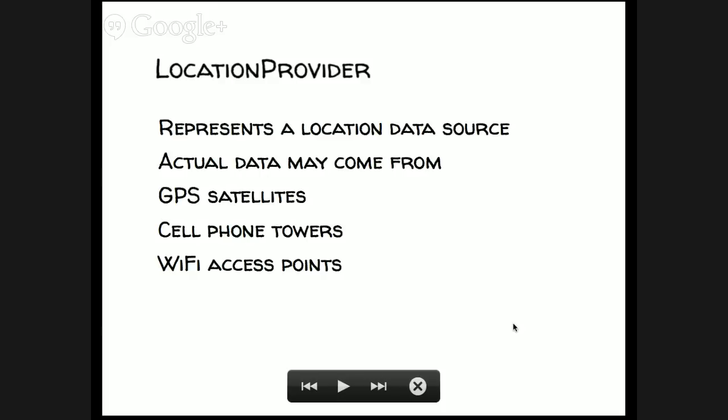You can see sometimes your signal bars are very good, sometimes bad, and then again very good, because it is fluctuating between different towers. It's sometimes connected to the tower on the right, and otherwise to the left, back and forth. So it is constantly hearing all these towers, and whichever gives the best signal strength, which is how well it can hear that tower, it selects. So what the Android operating system uses is the same concept. Instead of GPS satellites, you have cell phone towers.